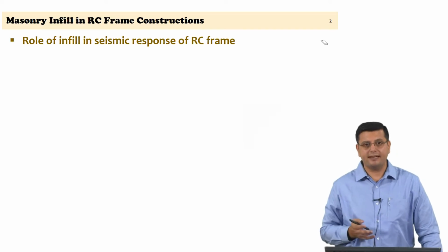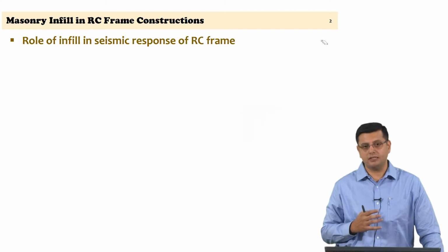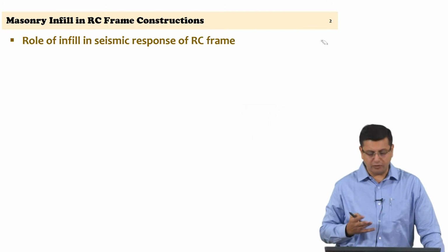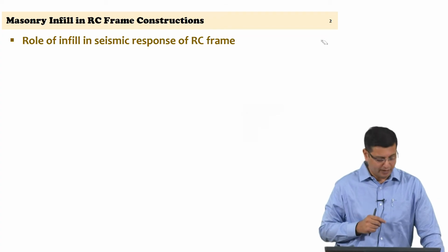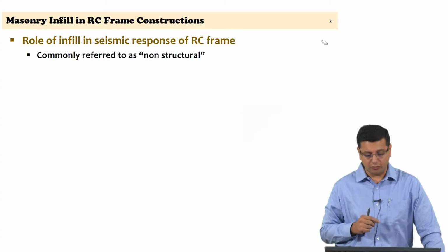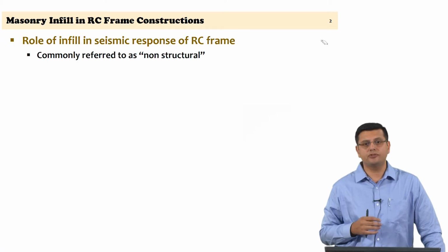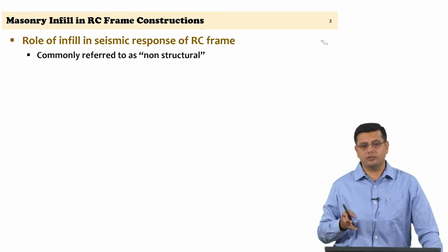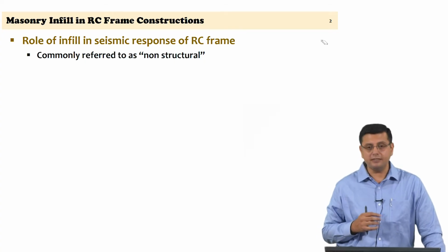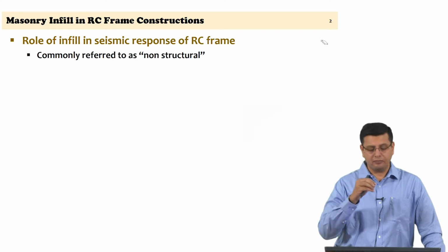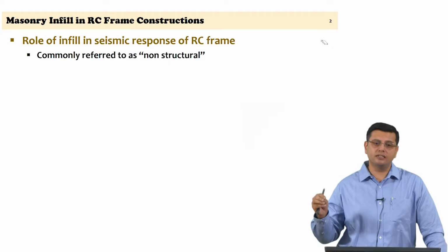So, the focus, as I said, is primarily the earthquake response of reinforced concrete frames. The role of the infill is going to be examined as far as the earthquake response of a reinforced concrete frame is concerned, but the standard practice has been to consider this as a non-structural element and use the role played by the infill only in terms of the mass modeling.